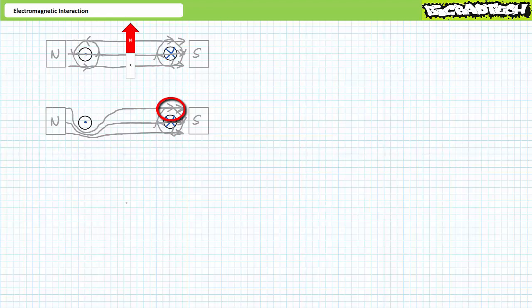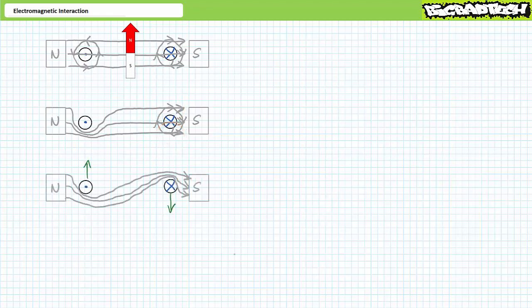Similarly, note the magnetic field on the top of the right-hand conductor is aiding, whereas the magnetic field on the bottom of the right-hand conductor is opposing. These fields coalesce so that there are less lines of magnetic force on the bottom and more on the top. The unified magnetic field on the top acts to push the right-hand conductor downwards. Given the left and right conductors are in fact cross-sections of the same three-dimensional coil, this coil will be torqued clockwise as the magnetic fields seek alignment.